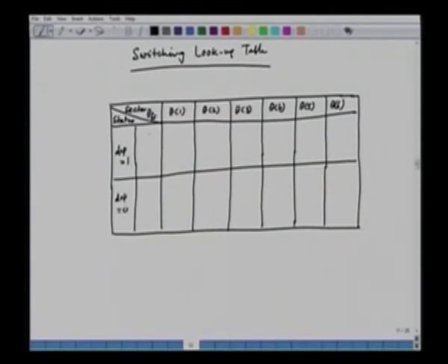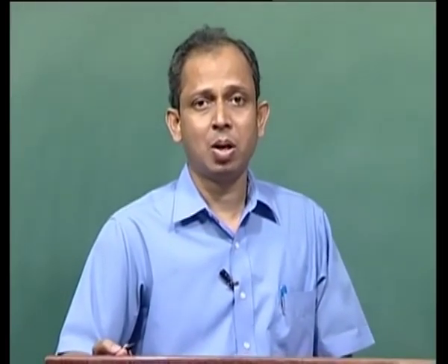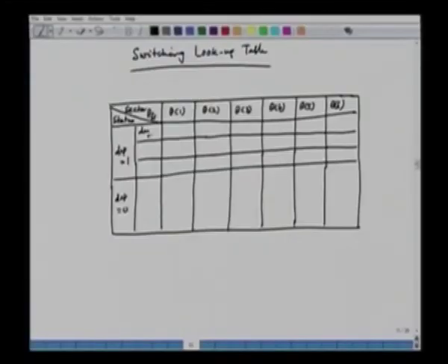And similarly, we can have the torque status. As we know, the torque status can be of 3 values. It can be +1, 0, and -1, because we have a 3-level torque comparator. So dm is equal to +1, dm equal to 0, and dm equal to -1.